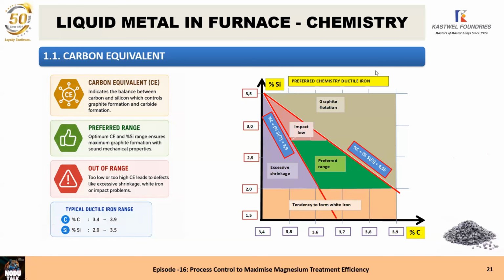With a wire in a ladle of 10, 15 tons, you cannot treat the metal properly, because that small wire treats the metal around it, but the diameter is so big and the amount of metal is so big that it's not possible. But if you come to smaller, less than 5 ton, then the tundish cover has been proven to be very, very efficient.